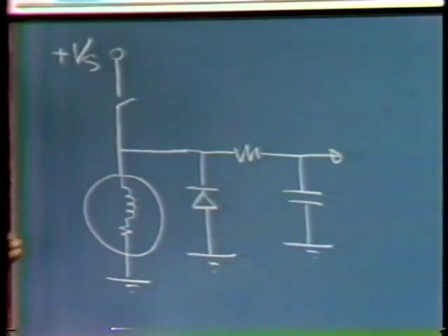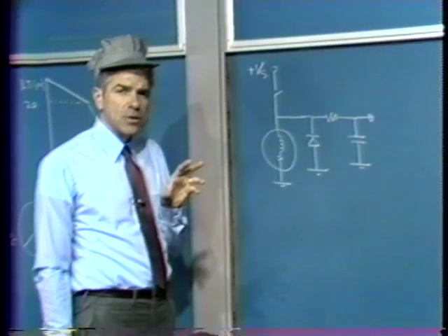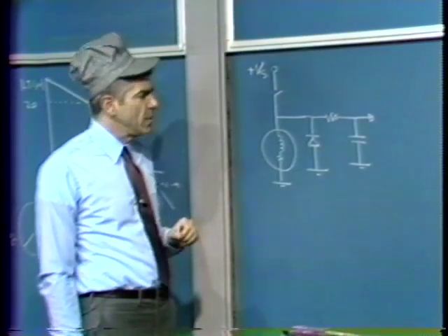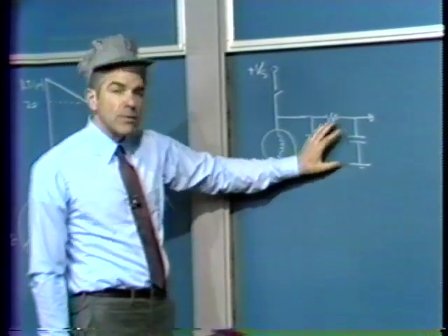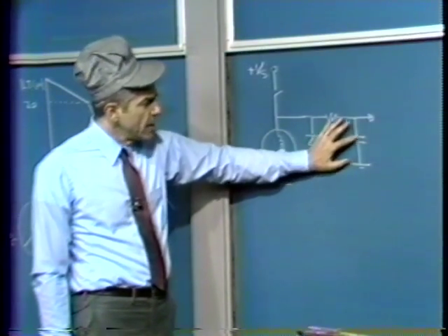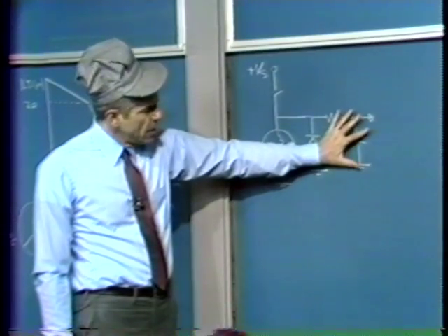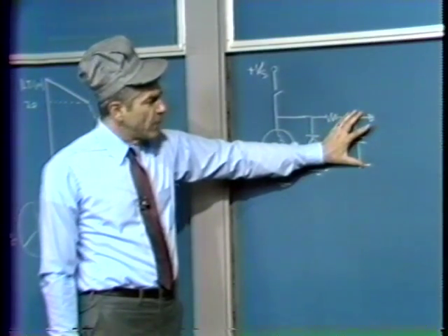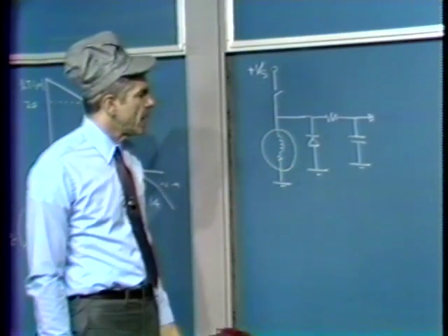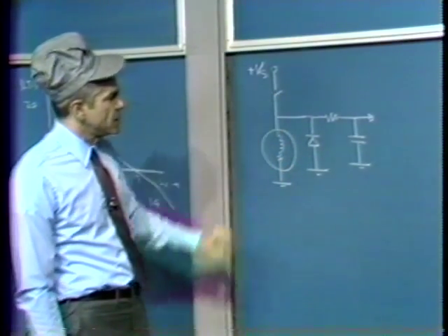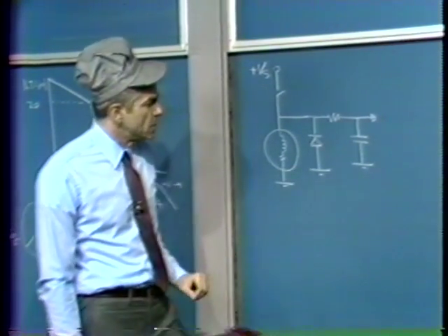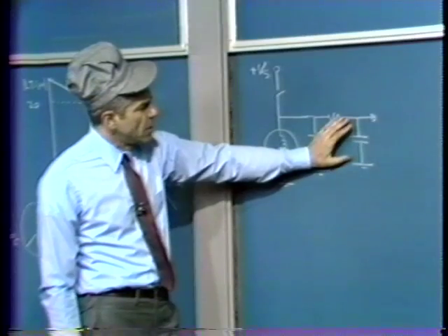And so what we do is apply our D to A output, the output from our digital analog converter, to this sort of a switching amplifier. We close the loop around the switching amplifier with this little low-pass filter that effectively forces the average voltage on the motor to be proportional to the voltage from the D to A converter. The technique for affecting duty cycle control is the part that was suggested by Professor Bose. In fact, he has a patent on it, as I recall.